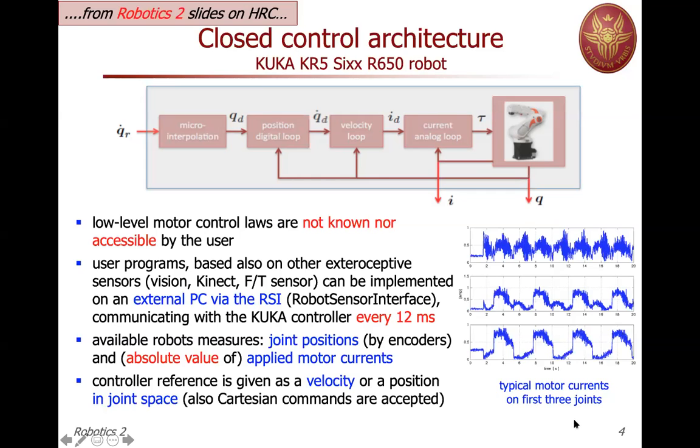So you don't care about the actual positive or negative value, nor even of the actual value, just if it goes over some threshold. So indeed, as we have seen in the language program, if you're using the program language of KUKA, the KRL language, you can specify joint velocities or Cartesian velocities, positions, poses, and so on.